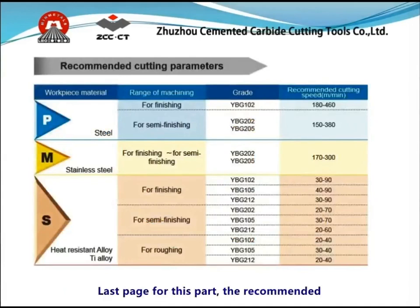Last page for this part, the recommended cutting parameters for PVD grades for P, M, and S materials, from finishing and semi-finishing to roughing, have been clearly structured. Due to the different characteristics of workpieces, for P materials finishing, the cutting speed can reach 180 to 460 meters per minute, and for M materials, generally 170 to 300 meters per minute. S materials are all below 90 meters per minute.